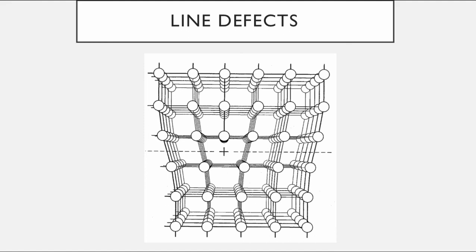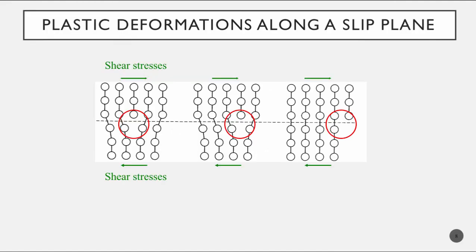That is going to cause shearing stress and some strains along the dashed line between the compressed and the tensile lines. And it is that behavior that actually leads to plastic deformation in metals, which is the coolest thing. As additional load is applied and shear stresses occur from the loading, it exacerbates the problem, and you literally will just tear apart along the dashed line.